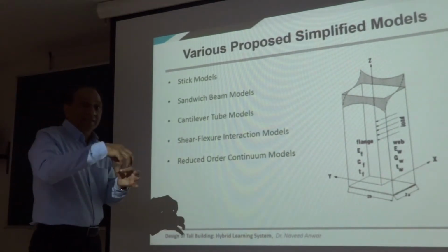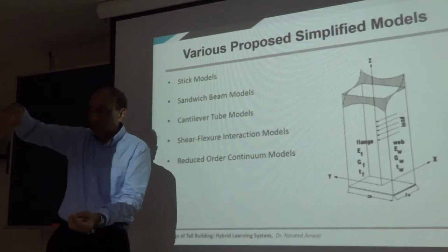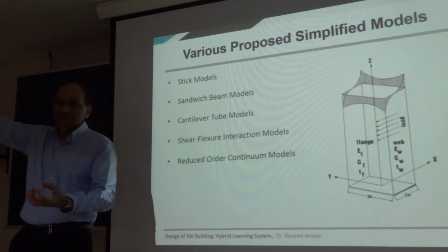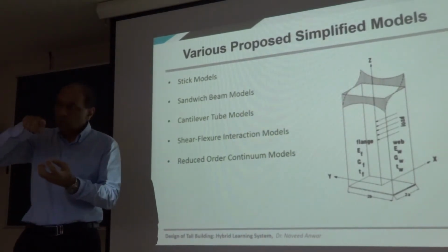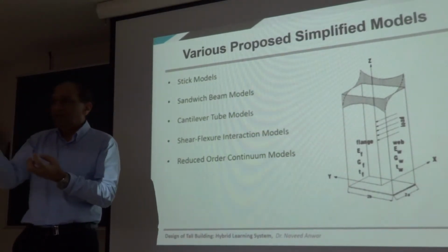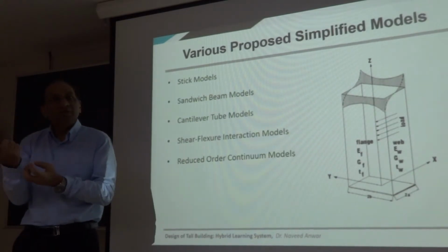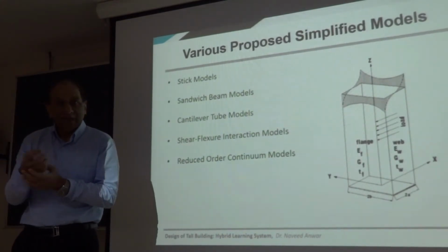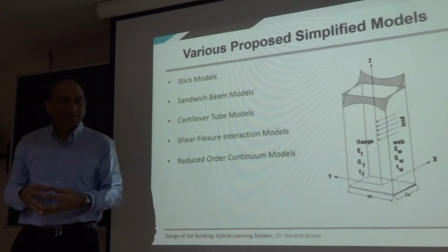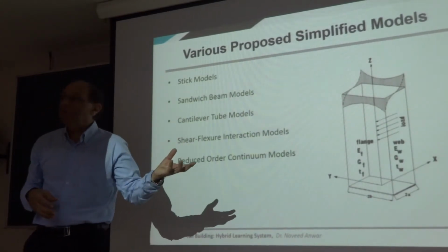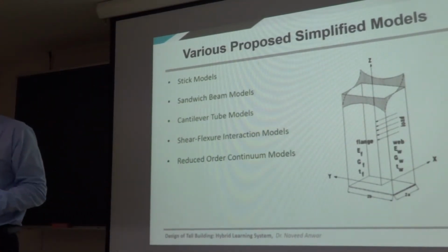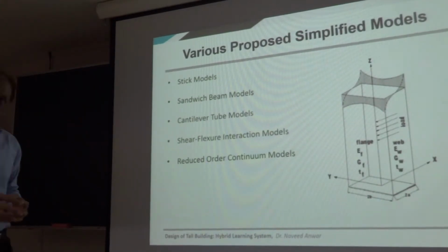But the point is that they considered at that time, even if you model the whole building, it is analyzed as a stick. One, they assume that each floor can only move in 3 directions. So only 3 degrees of freedom. A simple beam has 6 degrees of freedom. So basically we really reduced it to a very simple model, even in computers.